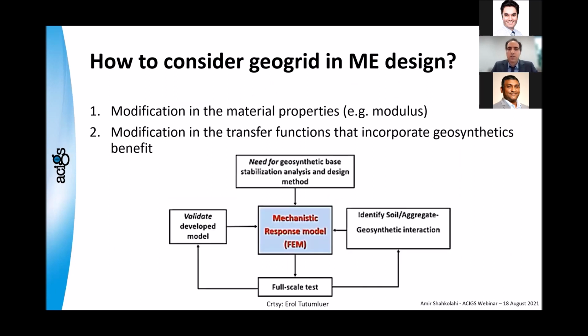This is a nice slide that I used. This shows, for example, a response model, a finite element model. These are the parameters that go in. We need a geosynthetic for base stabilization and design method. Then this clearly shows that the soil geosynthetic interaction is a very important parameter in the finite element modeling, for example, here. And that is why we spend a lot of time to talk about that. That's why we said it's an important part, because it's really important in ME design.